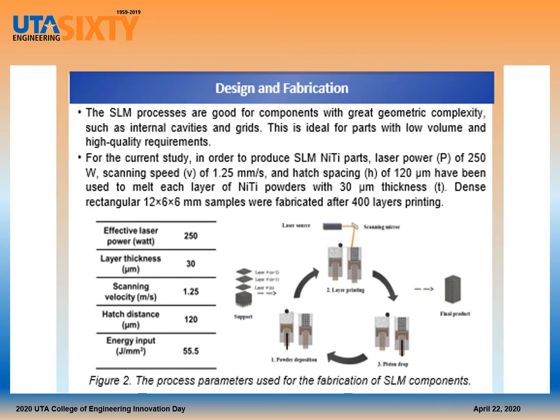The selective laser melting process is good for components with great geometric complexity, such as internal cavities and grids. This is ideal for parts with low volume and high quality requirements.